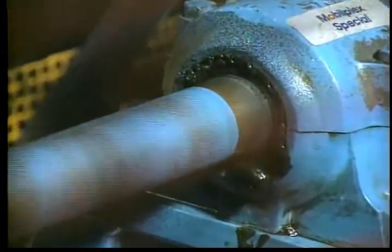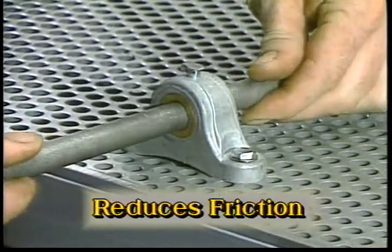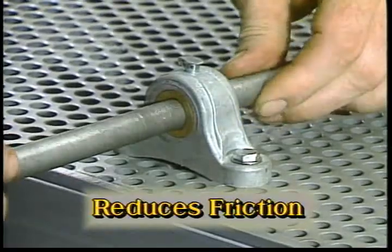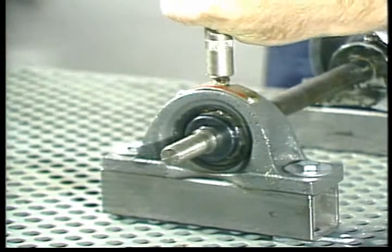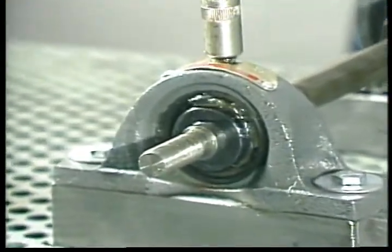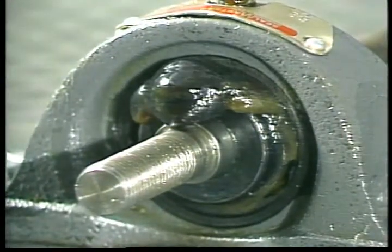Each bearing unit will have a different operating temperature, depending upon factors like speed, loading, and ambient temperature. Get to know what is normal for any unit, so you'll know when it's running hot. With a plain bearing, inadequate lubrication may allow metal-to-metal contact, producing friction and high temperatures. In a rolling element bearing, heat can mean that the bearing is completely dry, or it can mean the bearing is over-lubricated. Excess oil will churn, and its temperature will rise.